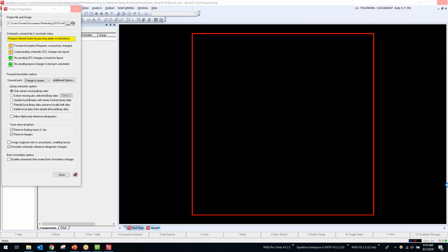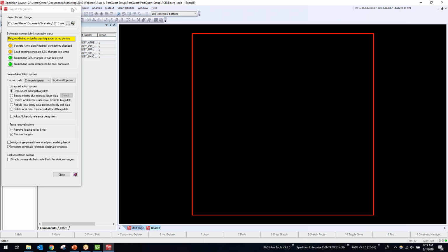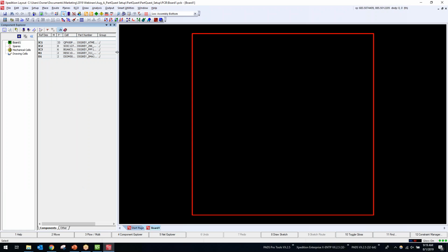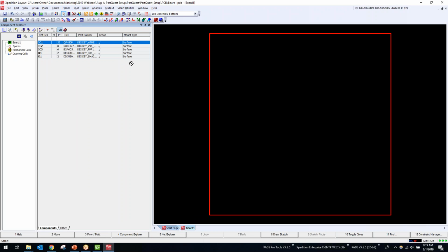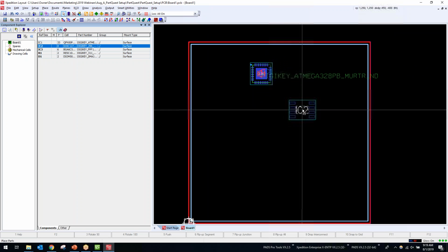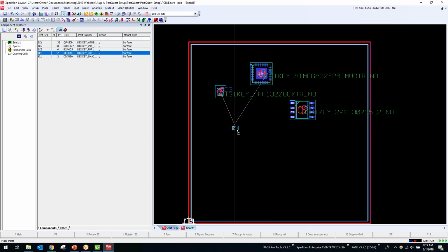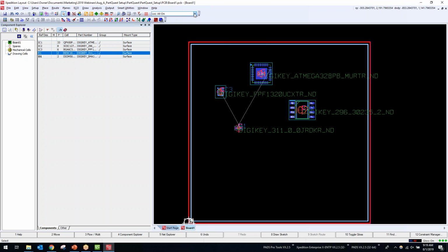Okay, I see another question from Conan, and he's asking about if we're able to place alternate cells. Okay, so even though we're downloading all of that data, can we have alternate cells? And yes, that's a great question, because we may not like the footprint that it gives us. And yes, you can definitely do alternate cells just like you do in any other Expedition library format. Okay, so that will allow us to create an alternate cell for those parts.